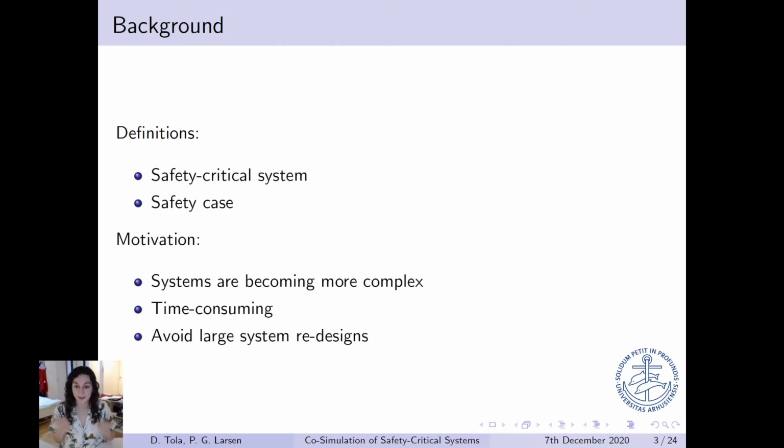I mean, this is part of being human, that we can make mistakes. And then they press the button down and the knife slices their hand off. So they would need to redesign the system to make sure that both of the operator's hands need to press a button at the same time before the knife will actually slice the object. So this is just an example of how important it is to actually think safety in the design of the system during the development of the system.